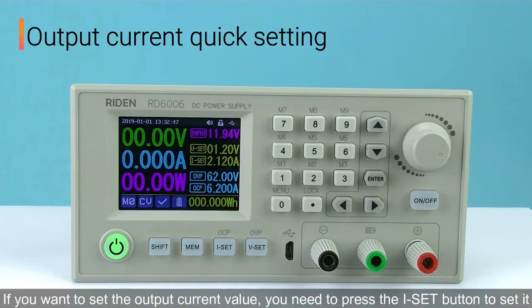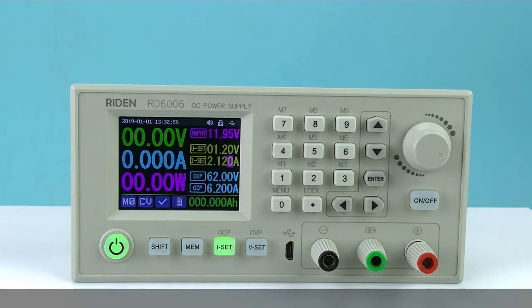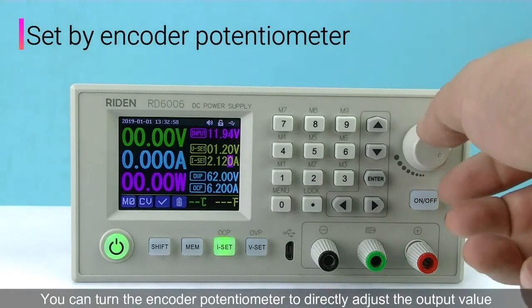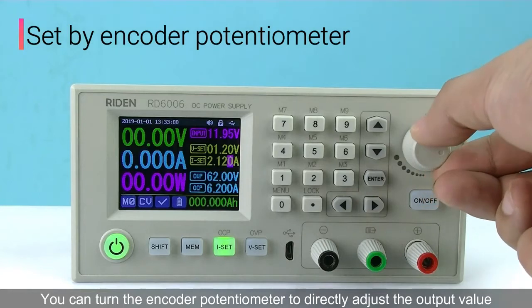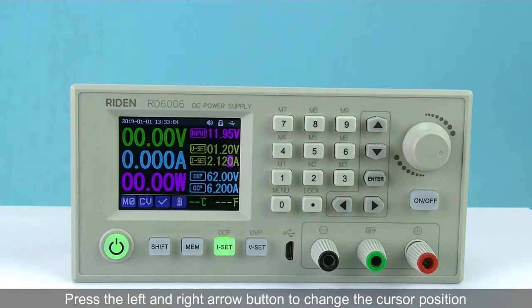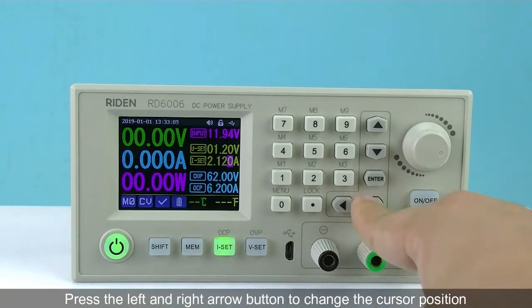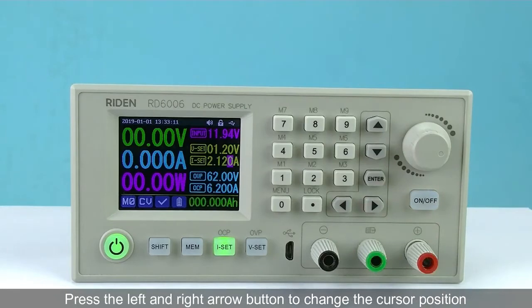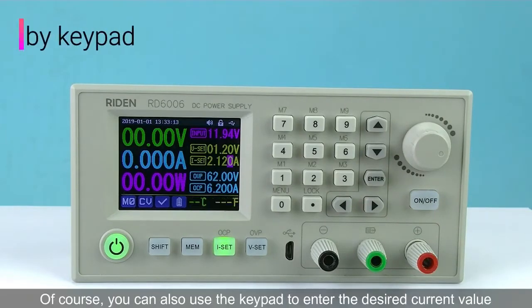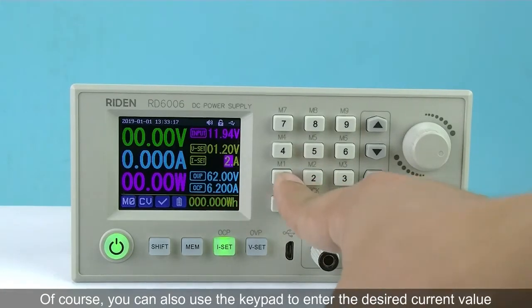If you want to set the output current value, you need to press the I set button to set it. You can turn the encoder potentiometer to directly adjust the output value. Press the left and right arrow button to change the cursor position. Of course, you can also use the keypad to enter the desired current value.